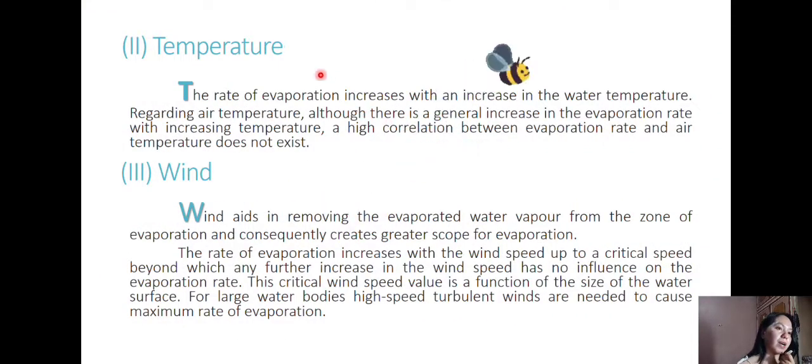Next is the temperature. The rate of evaporation is dependent on temperature. The rate of evaporation increases with an increase in the water temperature. Regarding air temperature, although there is a general increase in the evaporation rate with increasing temperature, a high correlation between evaporation rate and air temperature does not exist.